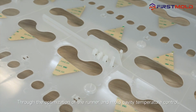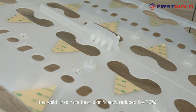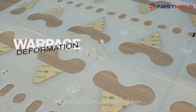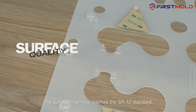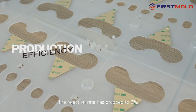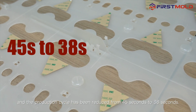Final results. Through the optimization of the runner and mold cavity temperature control, the weld lines have been significantly reduced by 90%. The warpage is controlled within plus or minus 0.3 millimeters, reaching the top level in the industry. The surface finish has reached the SPI A2 standard, meeting the requirements of the high-end automotive market. The rejection rate has dropped to 2%, and the production cycle has been reduced from 45 seconds to 38 seconds.